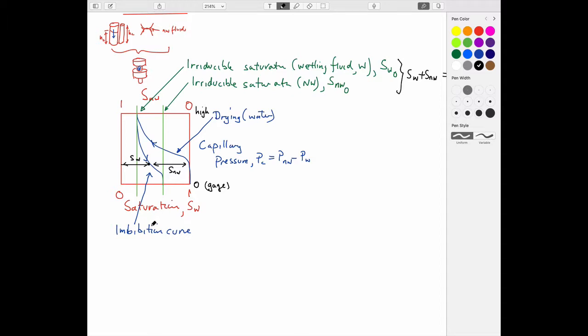And so those are the key features. One other one, what else did we talk about? We talked about this pressure here. This was what we call the bubbling pressure, or the entry pressure. We're defining this as a precursor to be able to talk about when breakthrough happens and what the distribution of saturations in the subsurface is.